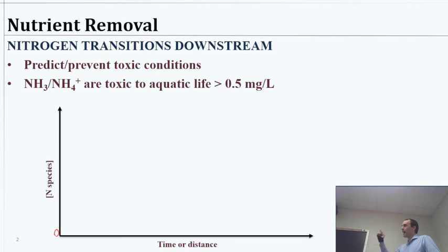Because early on, there's not enough bacteria that can take it through the nitrogen cycle. And so you'll end up accumulating too much ammonia, which is toxic to fish. If not that, you might get too much nitrite, as we'll see. So if you have a sudden input, new fish or some discharge of organic nitrogen, you'll have some formation of ammonia for a little bit, and then over time it'll be taken to 0.